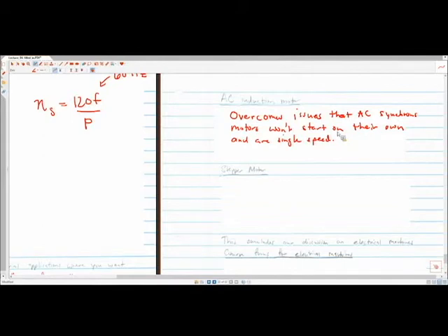Consider a case where the rotor speed is the same as the magnetic field speed. Since both are rotating at the same speed, the rotating loop will always experience a constant magnetic field. So there won't be any induced EMF and current. This means zero force on the rotor bars. So the rotor will gradually slow down.